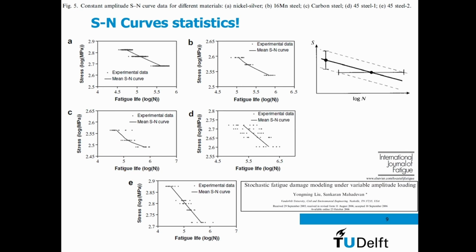So although we pretend that we can calculate fatigue levels and utilization factors just below 1, 0.98, be aware that this is in the end all based on statistical data of test specimens.